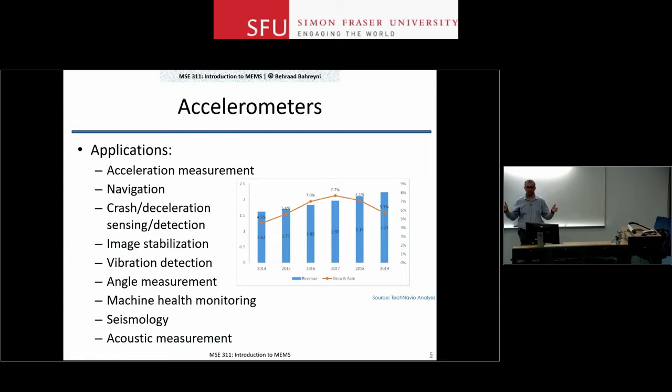They have a bandwidth of about 5 kilohertz and a sensitivity of less than a micro-g per root hertz. And these devices, when you talk at this end of the room and they're located at the other end of the room, pick up your voice through the vibrations of the air molecules caused by somebody speaking.